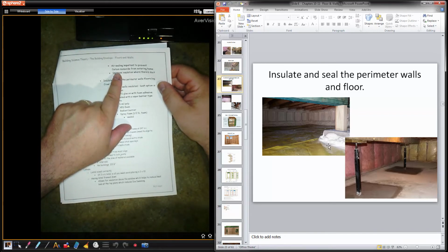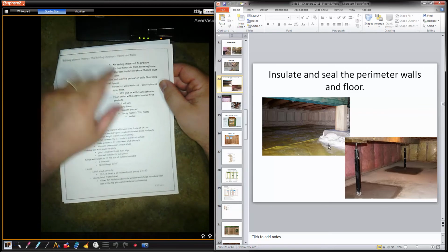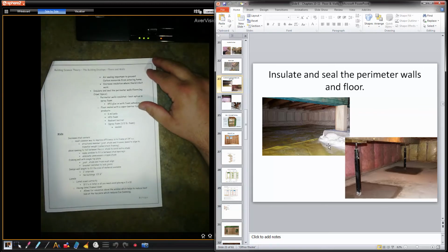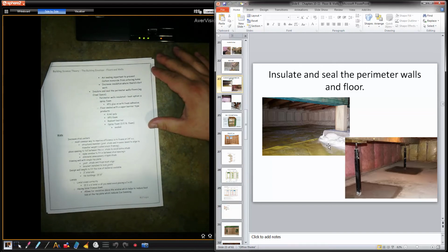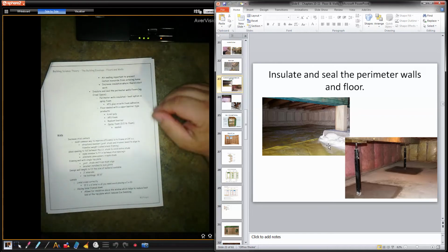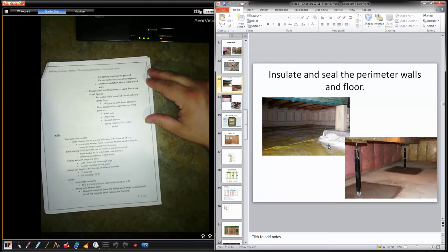So probably a layer of drywall on the bottom of that, and one coat of mud is required to create the fire protection. So if we had a room above a garage, the underside of that floor would have to be, first of all, vapor. You need thermal, air, moisture, and then you need to have fire protection. So a layer of drywall and one coat of mud on the seams, so paper tape and one coat of mud minimum to create the fire protection.